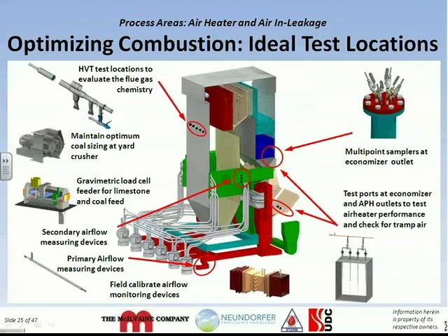The excess air that leaks into a suction-fired boiler is measured by an oxygen analyzer, just the same as air that was admitted through the wind box. This is an industry-wide problem, and it is very much underappreciated. Air in-leakage can result in heat rate penalties on the magnitude of 300 BTUs per kilowatt hour.